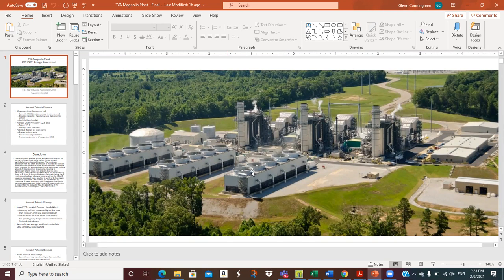This is the cooling tower for the condensers. So they don't have the hyperbolic. They're running 5 cells per unit, 15. Each one of these motors is 200 horsepower. So they got a megawatt per cooling tower.